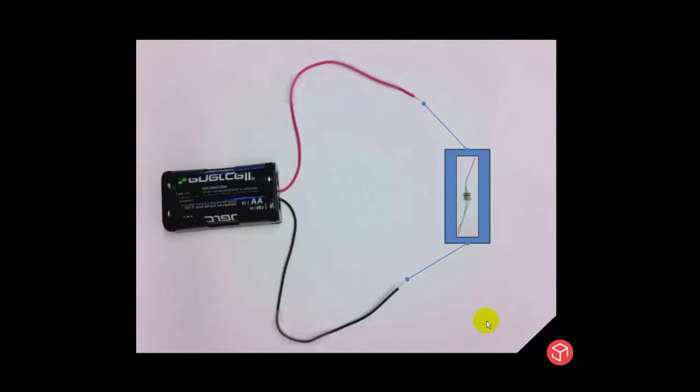Let's take an example that demonstrates Ohm's law. Suppose we have a power source supplying 3 volts, and an ohmic load, where I put a resistor of 10 kilo ohms. How many amps will flow through the circuit? The answer is 0.3 milliamp. Why? Ohm's law says V is equal to R times I, so I is V over R. 3 divided by 10,000 is 0.3 milliamp.